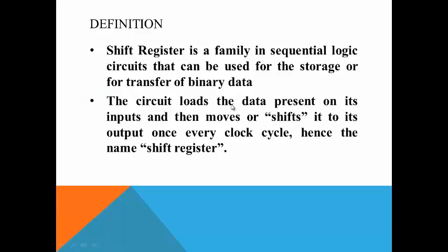Now this shifting operation leads to multiplication and division, but we have a family of circuits called shift registers. It's a family in the sequential logic circuits, and it can be used for data storage and transfer of binary data in parallel format or in serial format. These two are the basic types of data transfer: parallel transfer or serial transfer. So shift registers can be used as storage elements and also for shifting the data.